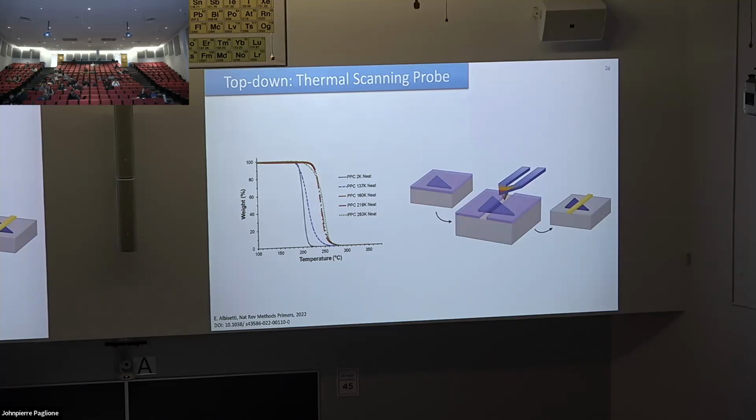So this is the approach for using this technique. You have some substrate, maybe a 2D material on top, and then on top of all of this, you have one of these resists that you can evaporate. You then come in with your thermal probe. You heat it up, you define some pattern in your software, and it just writes that pattern out and checks with the feedback loop of topography that you're getting what you want. And then you can evaporate metal on top, or you can etch, or whatever you want.